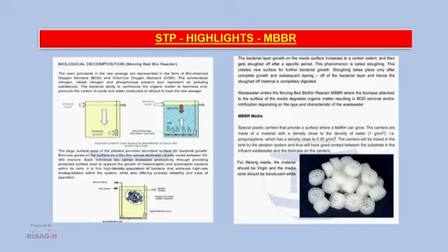The bacterial layer growth on the media surface increases to a certain extent and then gets sloughed off after a specific period. This phenomenon is called sloughing. This creates new surface for further bacterial growth. Sloughing takes place only after complete growth and subsequent dying of the bacterial layer, and hence the sloughed material is completely digested.